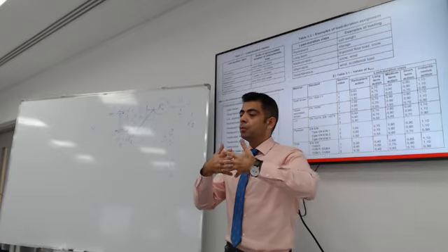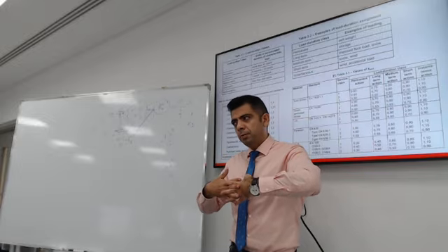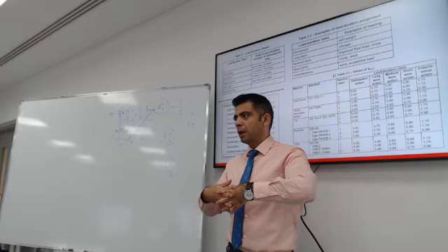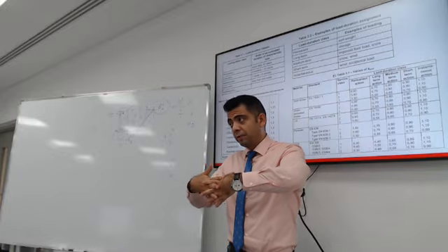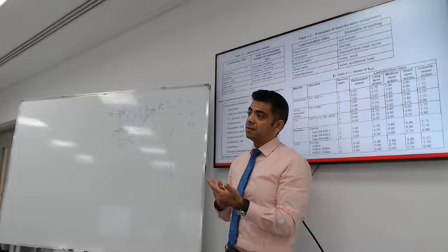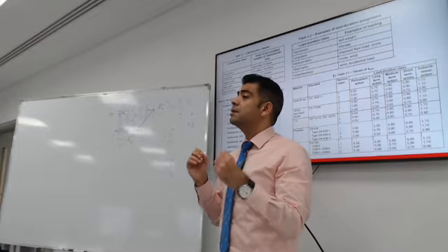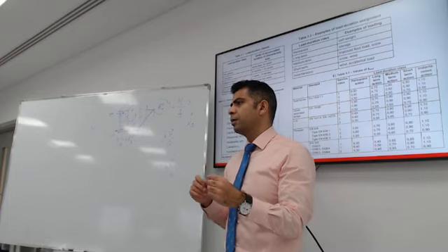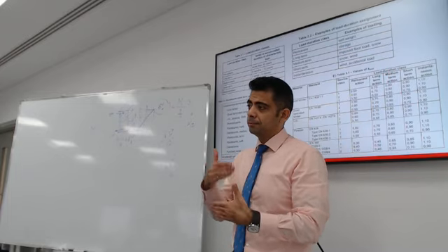Because if you put a heavy load on wood for too long, creep might need to be taken into account. Over time, with the exact same load, it might deform with time. So if it's a permanent load, I need to take some factor into account. If it's an instantaneous load or a temporary load, can you think of an example of a temporary load on a wood structure?